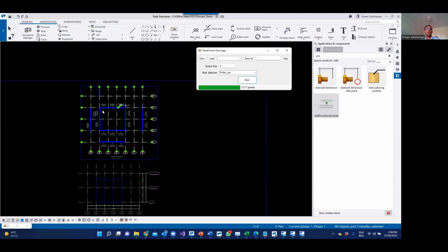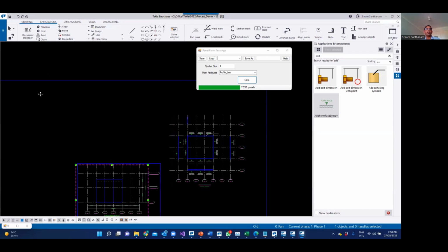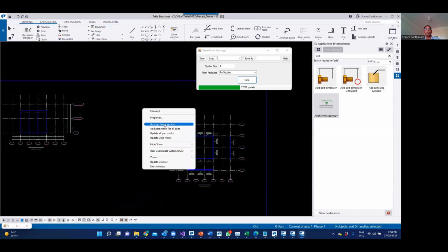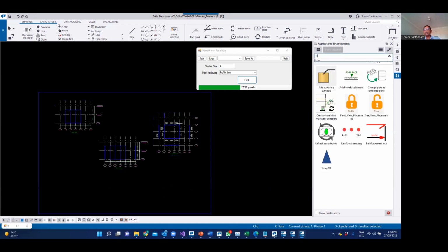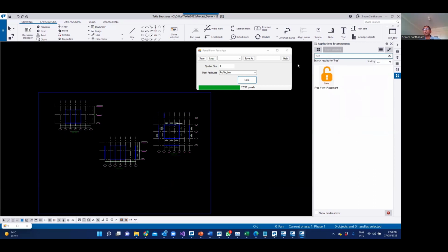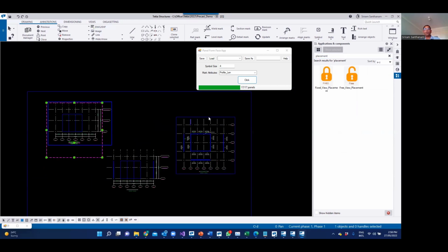And the one last thing is that sometimes we move the view, and once you move the view, obviously we cannot use this arranged drawing views because it will not move the fixed view. And I'm just giving these for free. If anyone needs this placement, let me know. These are the fixed ones. So now I can select because I moved this one. Once I click free, it will automatically make this view free to move now.